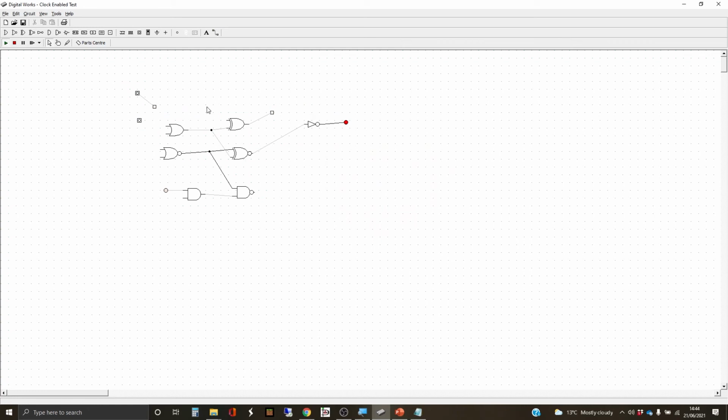So, in terms of the circuit, you can think of each gate as having several inputs and one output. The principle is that you cannot connect two outputs together, but you can connect an output from an entity to as many different inputs as you like. The thing that's called an interactive input, in terms of the circuit, has one output. And the LED, which you could think of as being an output, actually just has an input.